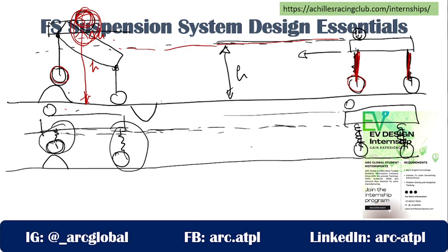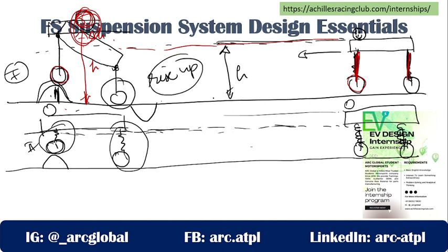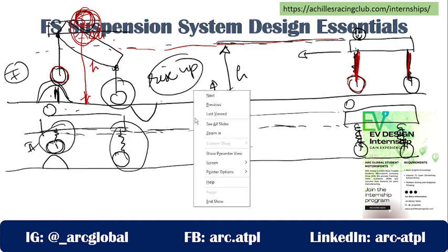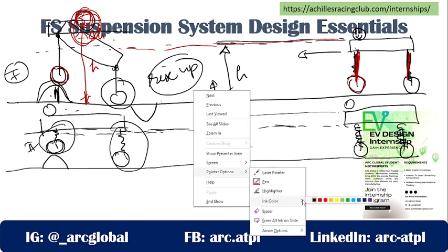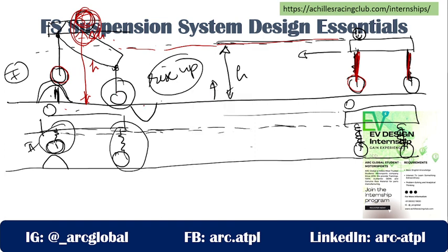Now there are also chances, my dear friends. If the bump height in the first diagram is way too high, then what will happen? There are high chances that the rear tire will also rise up from the ground. If the rear tire rises up from the ground, it will not maintain the required traction between the road and the tire, hence making your vehicle unstable.